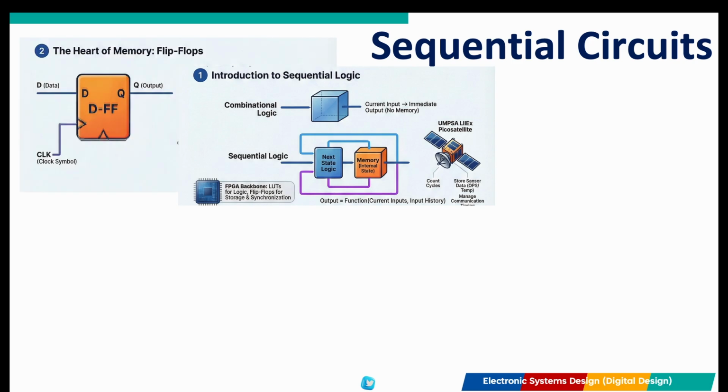The most critical building block in a sequential design is the D flip-flop. Think of it as a single bit checkpoint. While a basic gate reacts immediately, a flip-flop is edge-triggered. It ignores its input until it sees a tick from the system clock, usually the rising edge. At the exact moment, it captures the input data and holds it steady at the output until the next clock tick. This synchronization prevents errors by ensuring every part of your circuit moves in perfect lockstep with the clock.